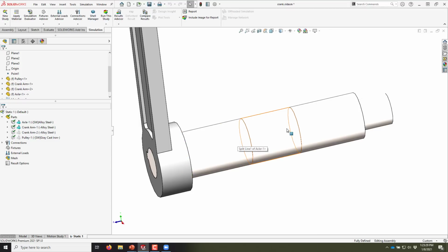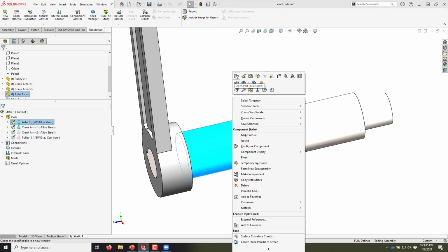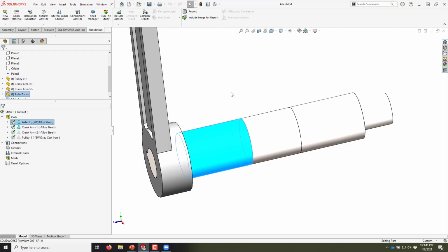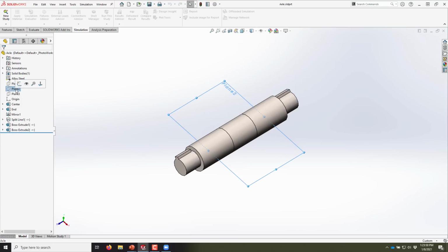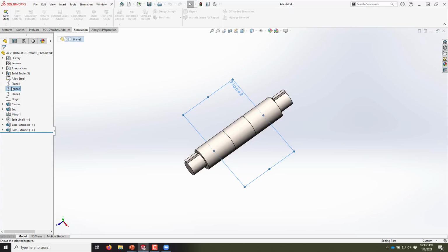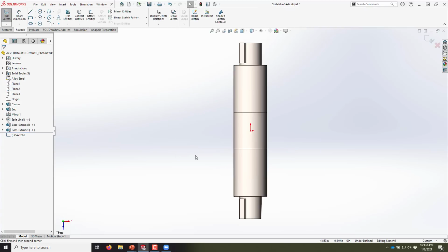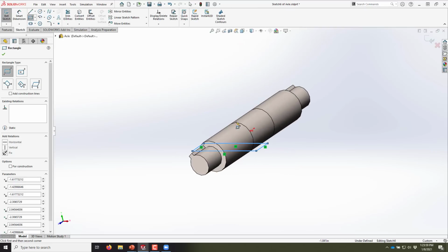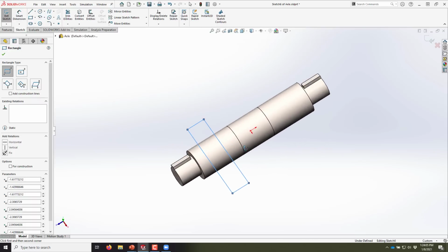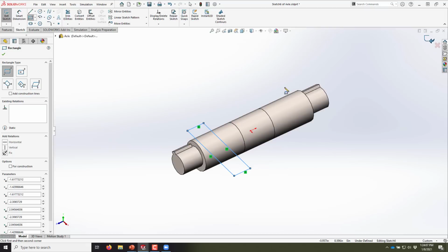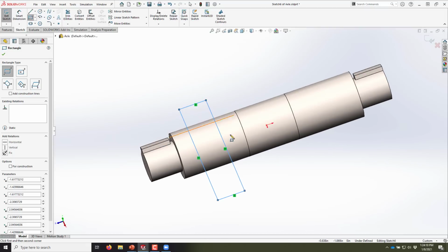I'm going to show you creating a quick split line. How do you create this type of thing? If I open up this part, it should be in a part modeling mode of some kind, either editing a part in assembly or open up the part. In this part, I'll add a sketch onto, you kind of see this plane here, I'll add a sketch onto plane 2, just for demonstration. And maybe I'll draw a sketch that looks something like that. Pretty similar to what I drew over here, by the way, for this split line. And what I'm going to do with that sketch is project it onto this big cylindrical face here. You'll see what it creates.